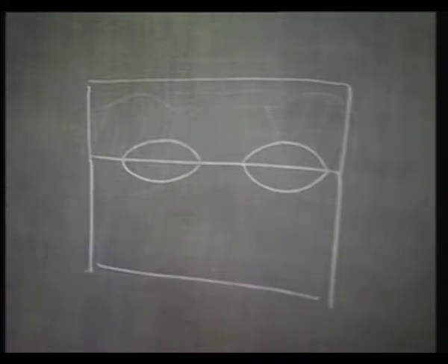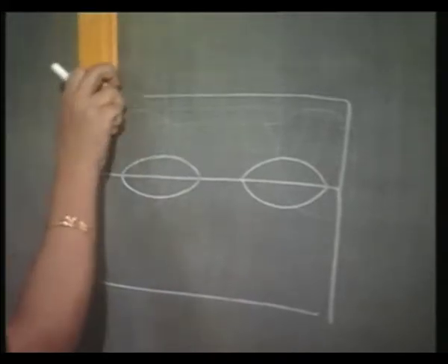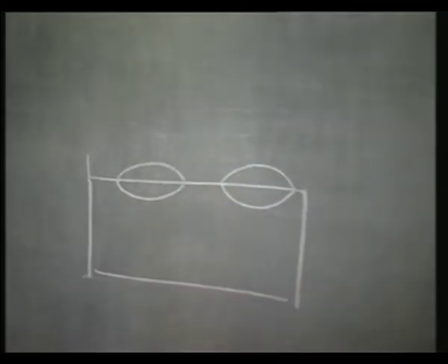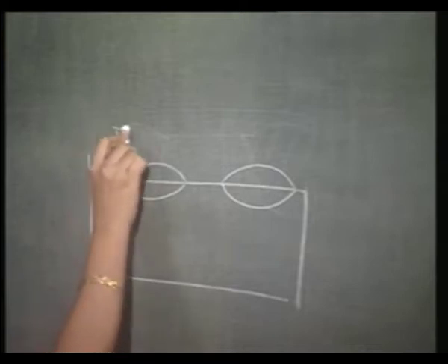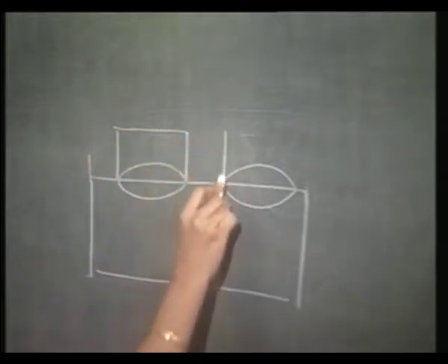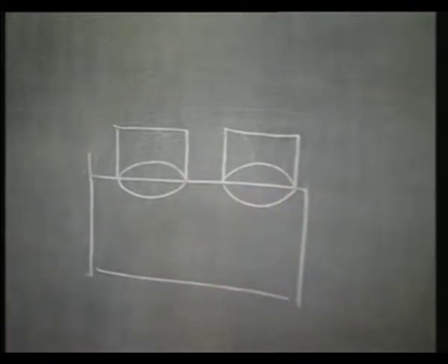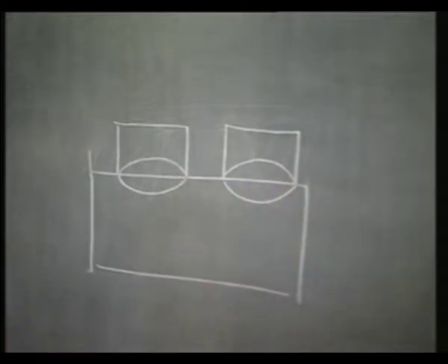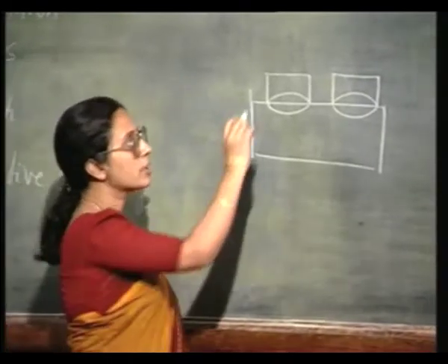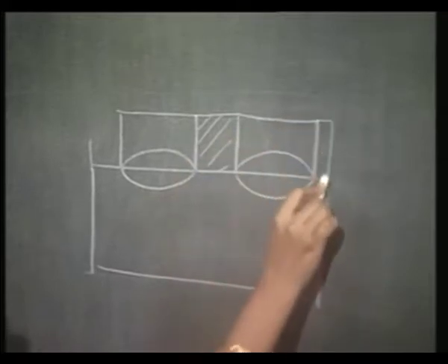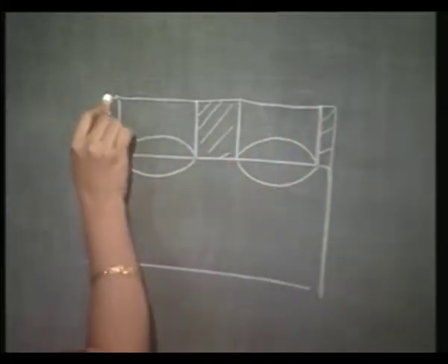Now, instead of doing this, why not grow epitaxial regions only on top of the buried N plus layer? If I can have that, then my problem of isolation does not even exist. And as far as planarity is concerned, I can have these regions oxidized.